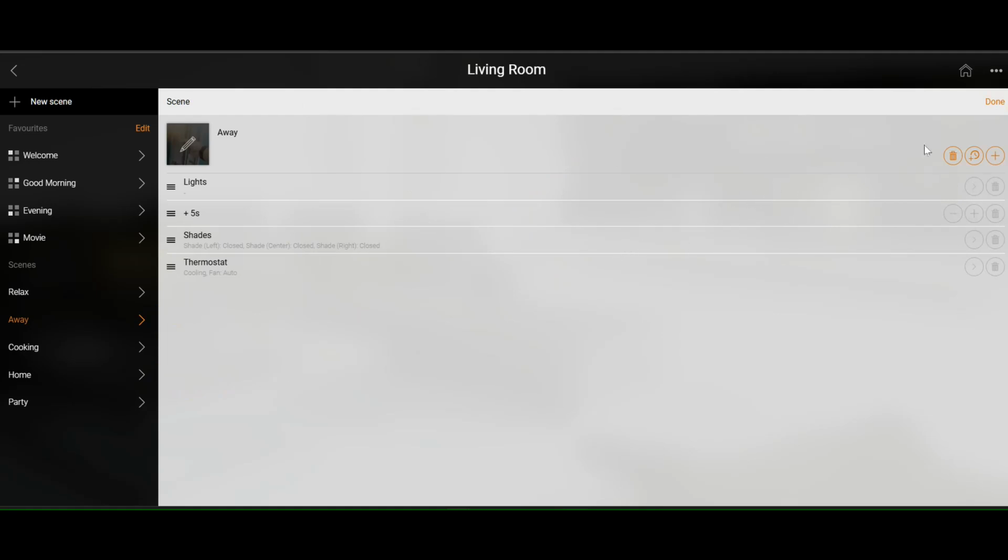So then when we want to save that, we can save it, and we can actually play it from here and see what we want. And if we push the button on any of the switches which are linked to the scene group address that are calling scene 11, then we'd expect to see this happening. So that means the scenes are very dynamic and the customer can change them. Again, the limitation is how many scenes the server can remember, but it does open it up to everything else that's available on the server.